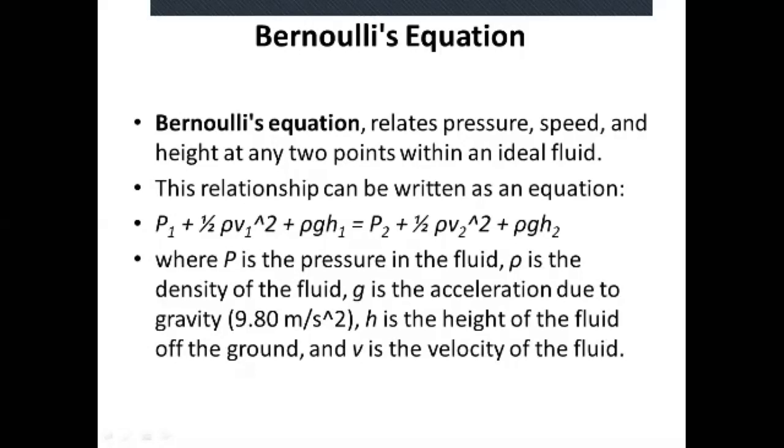When a liquid is flowing, there's a change in pressure, so we have pressure 1 and pressure 2. We are saying the initial energy should equal the final energy, from the principle of conservation of energy. So this is potential energy per unit volume, kinetic energy per unit volume, and on this side we have pressure. Is that okay?